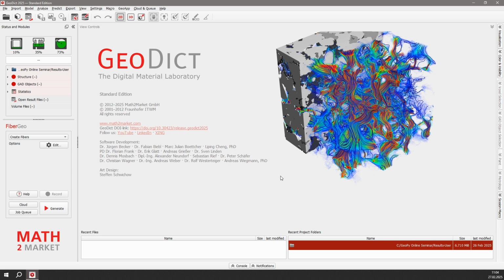There are two possibilities to save a macro. One way would be to first start macro recording and then execute the GeoDict commands that you want to record, and then end macro recording. The second possibility is to press Run and then save the commands afterwards. Both ways have their advantages, but we choose the second possibility in this workshop, which has the advantage that you do not need to know beforehand what you want to record. We can simply select the right commands afterwards in the session macro dialog.